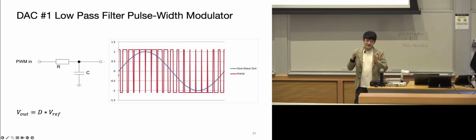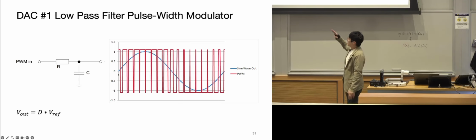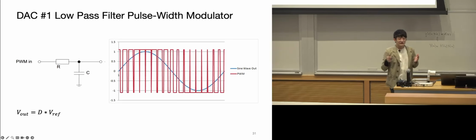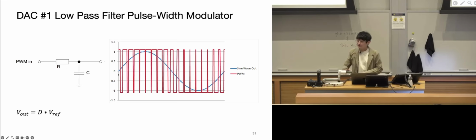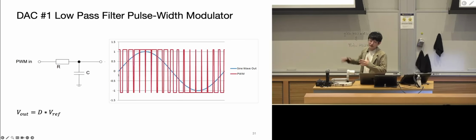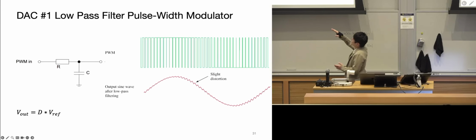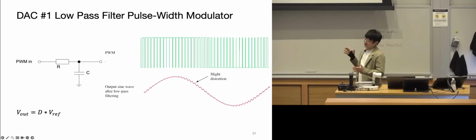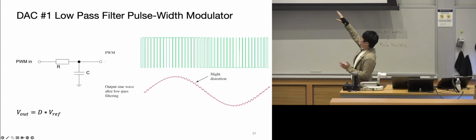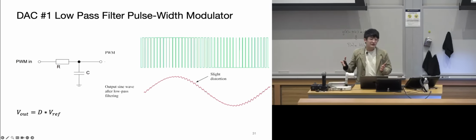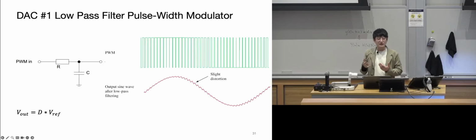It depends on the duty cycle you set based on your PWM output. And that can be conveniently used to convert to sine wave looking signals. For now, we will just talk about single frequency signals to keep it simple. Of course, in real life, the actual signal will not be that smooth. You will typically see spikes throughout this type of operation. But if your application does not care too much about performance, this will usually do.